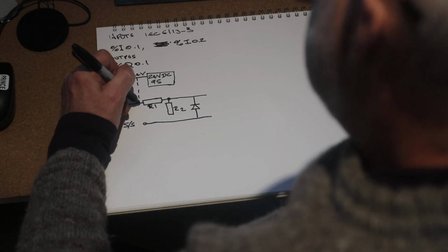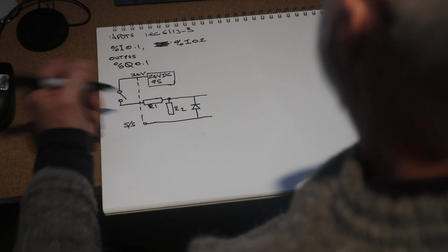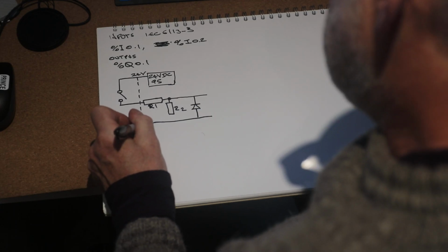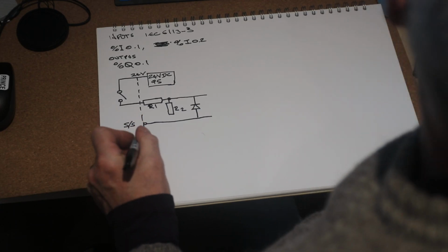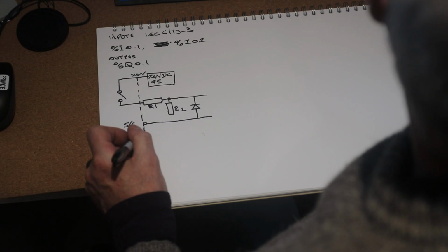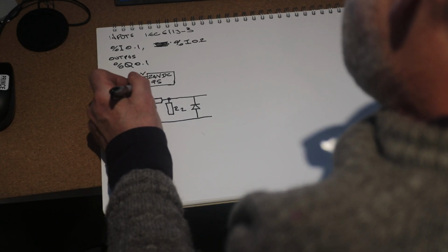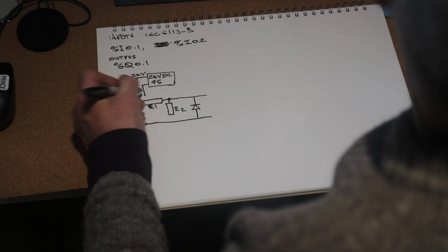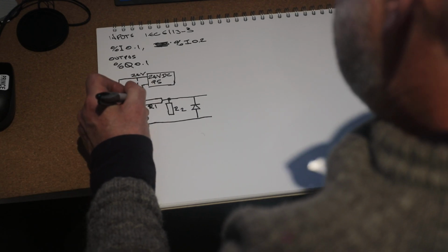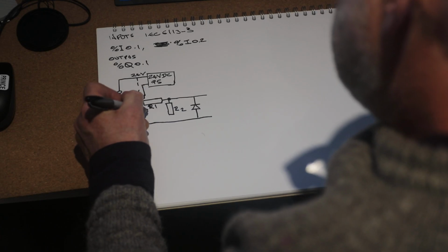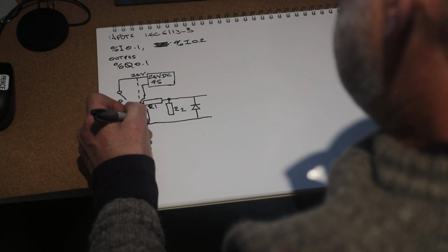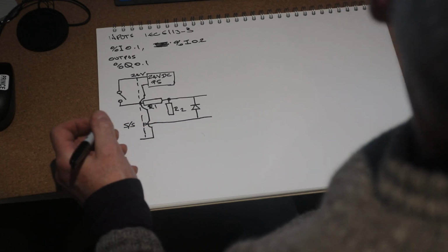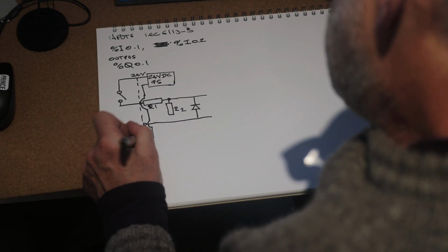What that means is you might connect sinking and sourcing to 24 volts, or you might connect it to 0 volts, which is down here, and that's going back to my power supply, which I'm now going to try and draw much better than I have. So it has to skip over there, and it has to skip over there. We've done that before, yeah. And I'm going to come down here and put my 0 volts in there, right?